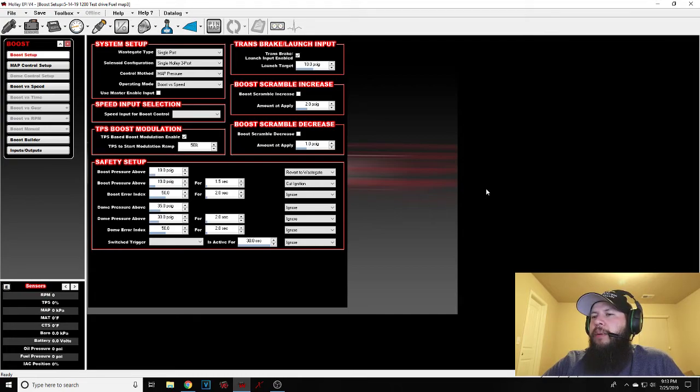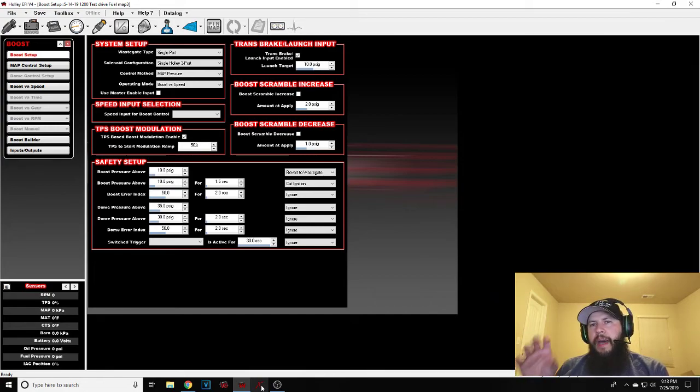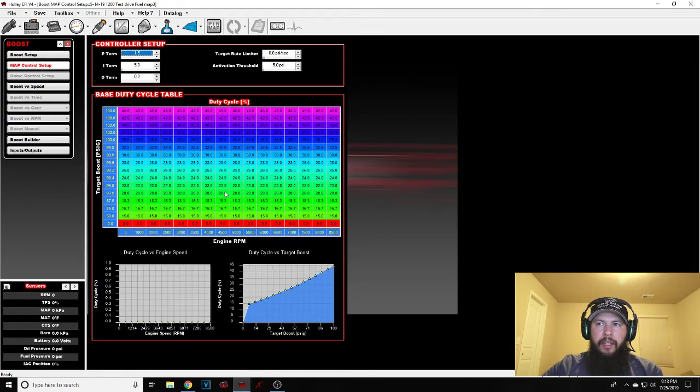The only other thing I would say: I was going to go into the Terminator X stuff, but actually what I would do is just search for the Sloppy Mechanics video. I think Matt just did a video recently of him taking the map sensor value, the actual signal, and putting that into the dome pressure input, so that in Terminator X you can basically do this same thing. You're just going to be tricking the ECU into thinking that it has a dome pressure input, but really you're going to be using the map sensor value.